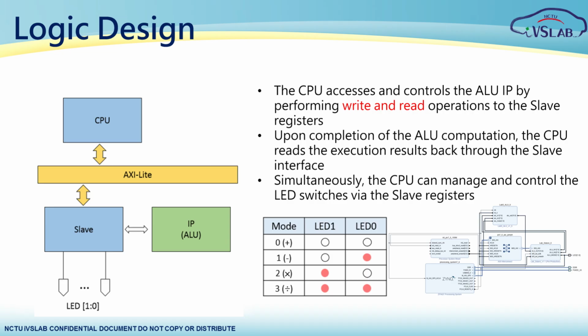After the operation is complete, the CPU will issue a read command, fetching the execution results back from the slave's internal registers via the AR and R channels. Additionally, the CPU can also interface through this exact same slave module to control the onboard LEDs. You can reference the actual block design layout right here in the bottom right corner.